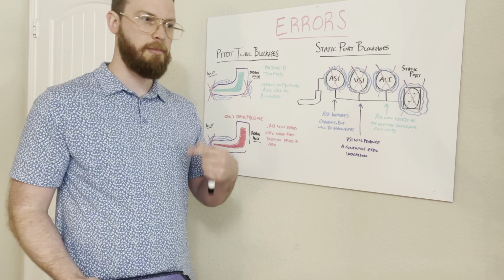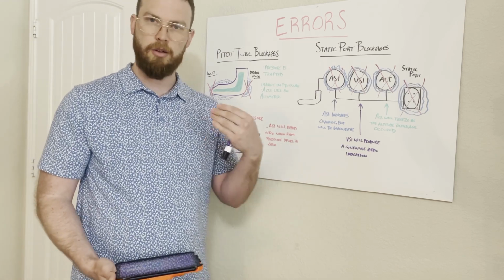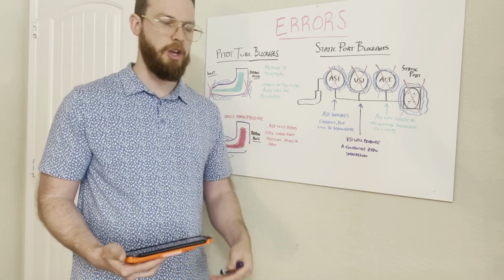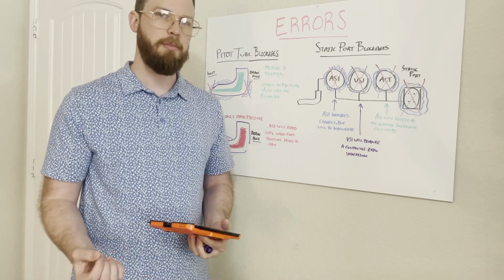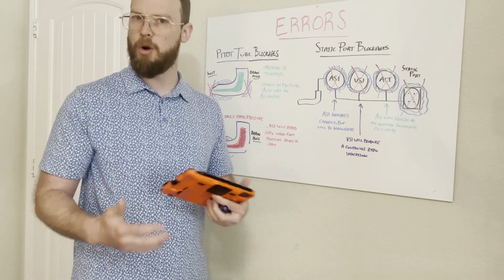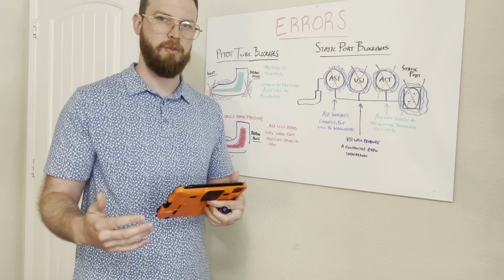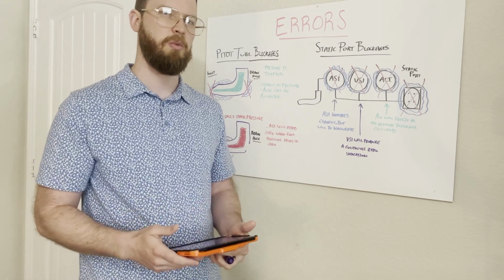So also know the performance of our aircraft. So knowing our climb rate, descent, normal cruise, things like that, knowing our performance profile in the POH or AFM, knowing these numbers is going to give us better clues of what's normal and what's a little bit out of that normal envelope and something that's a little bit weird.